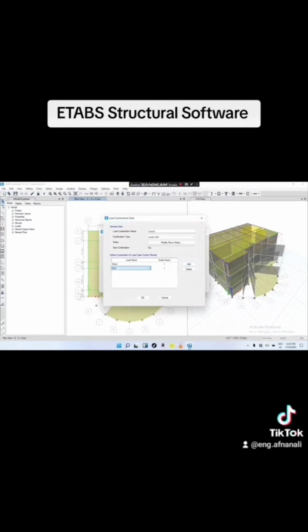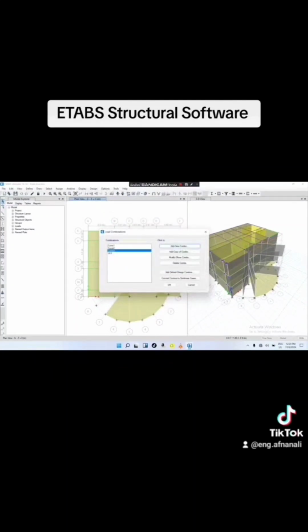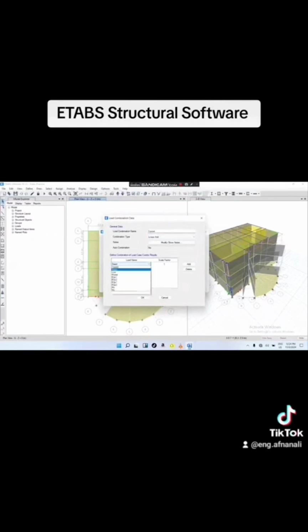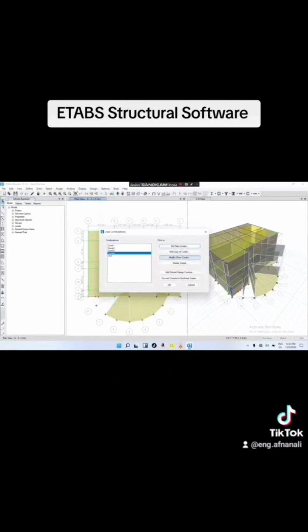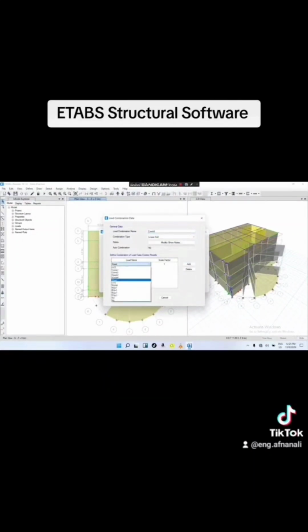I will add compo 3, the ultimate, which is 0.7 for the whole combination I will make now, and then EQX2 in the positive direction, +1. And then combination 4, which is EQX2 and the -1. For the EQX direction, make it 1 in positive, 1 in negative combination.